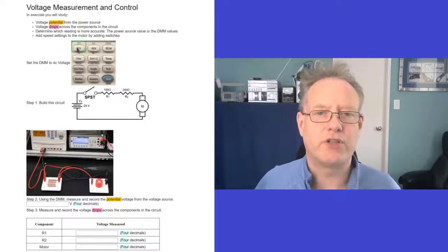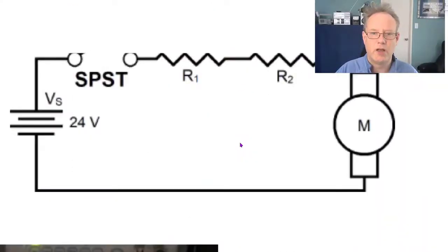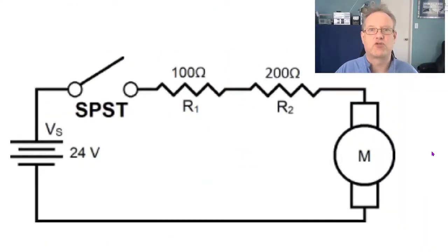And then you're going to measure voltage. So you're going to hook up this circuit, which is pretty cool. Let's just zoom in. It's really complicated. No, it's not. And you'll see how I did it in the lab. I actually hooked up the components the way that the circuit is. So when you're hooking the components up, place them on the board the way that you see them in the actual circuit. Do that with a breadboard too, if you use breadboards.